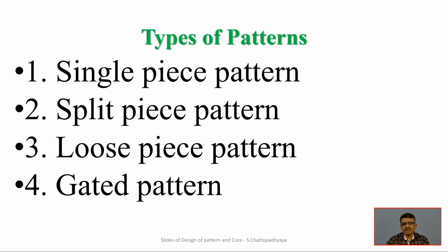So then and then only people go for the single piece pattern. Otherwise, single piece pattern removal is always a challenge if it is associated with very complex and complicated geometries of those cavities. And the second one is split piece pattern. So you split the pattern. Again, the main motivation here is in order to retrieve those patterns. So the pattern is split so that it is easy to retrieve from the mold to create the appropriate cavity.